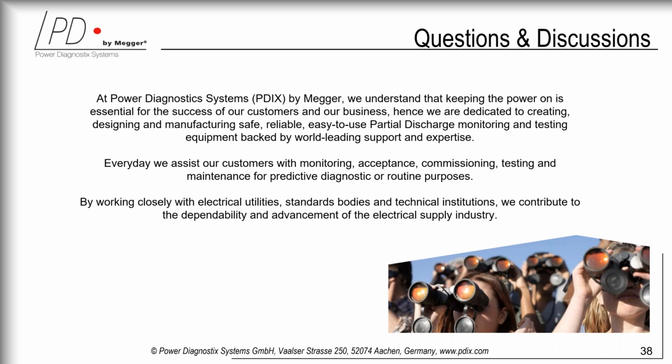All right. Next question is going to be from Marcus. Marcus, do you require reference voltage, and does it support DNP3? So the reference voltage is taken from the bushing coupling unit as well. So this small box on top of the transformer close to the test tap provides the PD impulse signal plus the superimposed voltage signal. So it's a capacitive divider built up between C1 of the bushing and CD built in with this box.